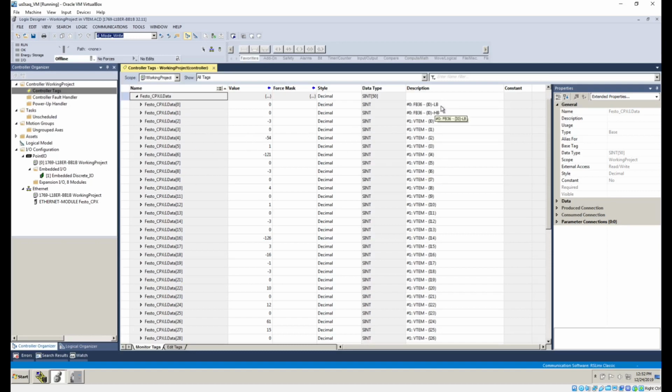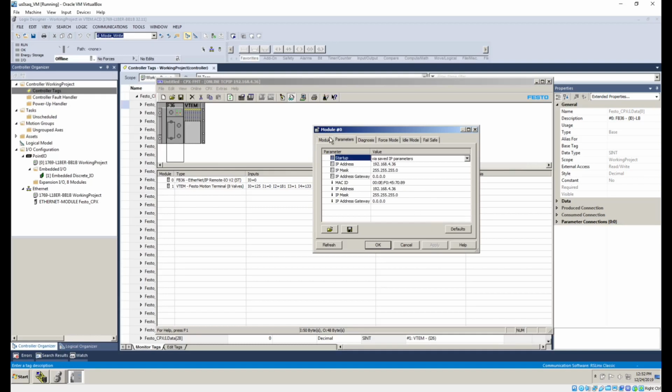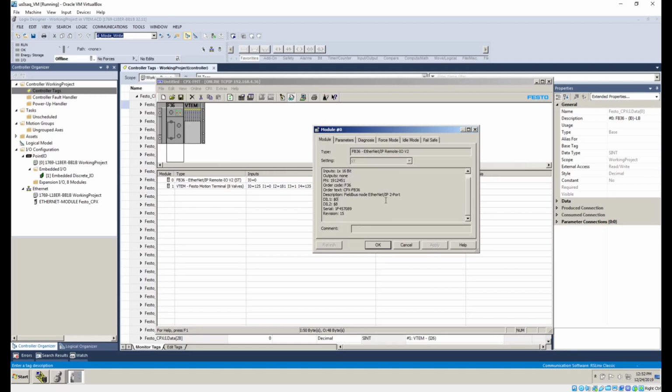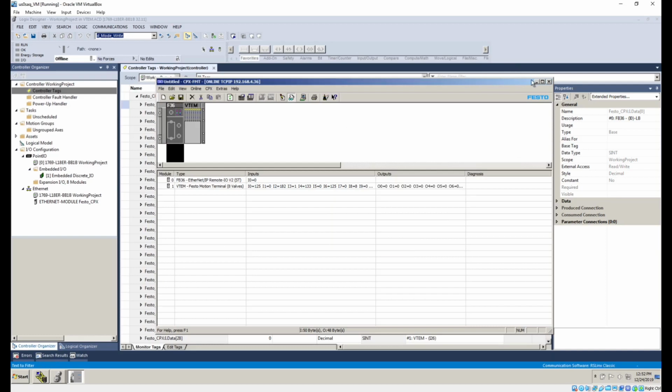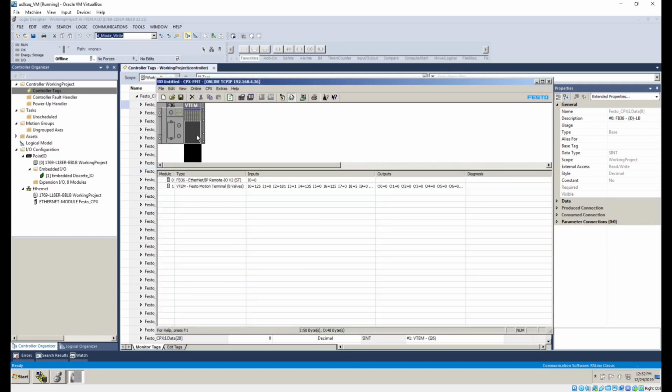So you can see these first 2 bytes are diagnostics because of the way that I have my module configured on the DIP switches. Here you can see the second group on the DIP switches on the module. I have one of the switches on, so it's sending me some diagnostics, in this case 2 bytes, and then the remaining bytes are for the valves, right? For this portion over here.